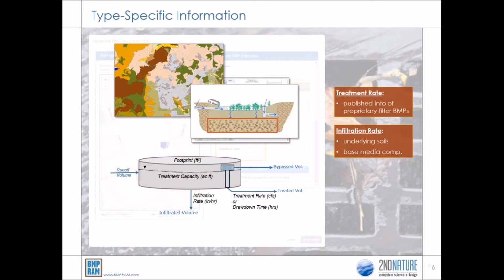Information on infiltration rates for various media can be found from the NRCS soil survey or other published infiltration rates based on the substrate type placed at the base of the BMP. We recommend that when using this approach, you consider the depth up to 4 feet below the surface and use the lowest infiltration rate. In the field, appropriate field techniques include ring infiltrometers or constant head permeometers. Multiple measurements must be conducted to represent the rates across the entire infiltrating surface of the BMP. Infiltration rates can also be determined through high-resolution monitoring and the development of a site-specific water budget.